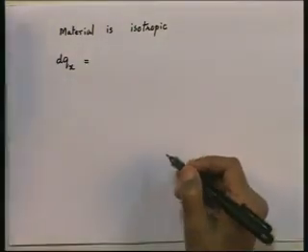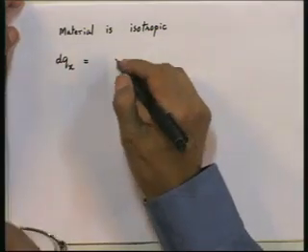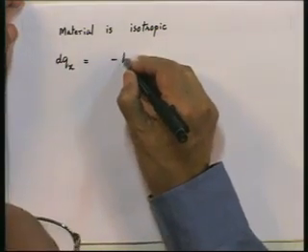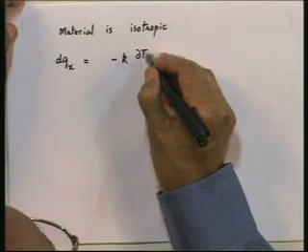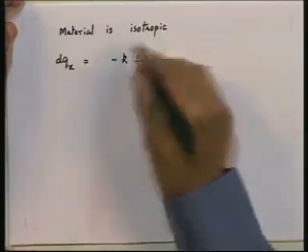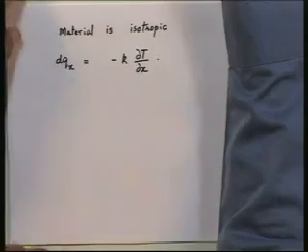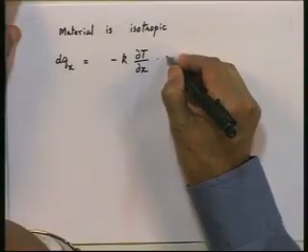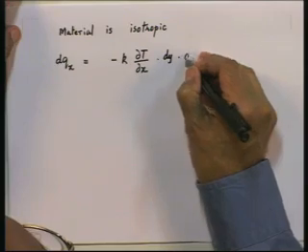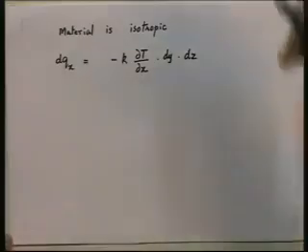By Fourier's law of heat conduction, dqx will be equal to minus k dT/dx, this is the heat flux in the positive x direction, multiplied, since we want the rate at which heat flows, by the area of that face, which will be dy dz. So many watts is the rate at which heat flows into this x face.